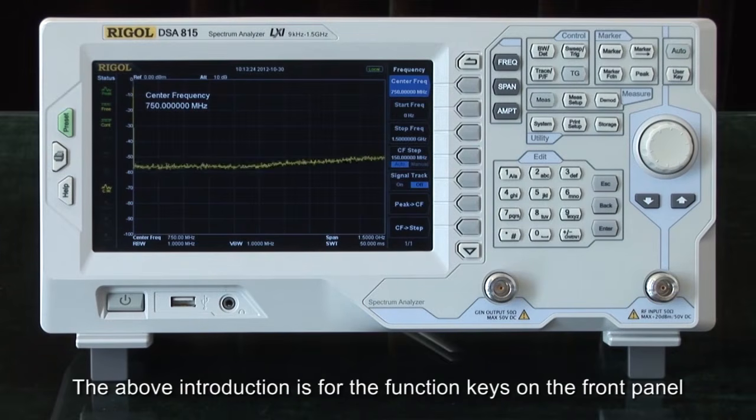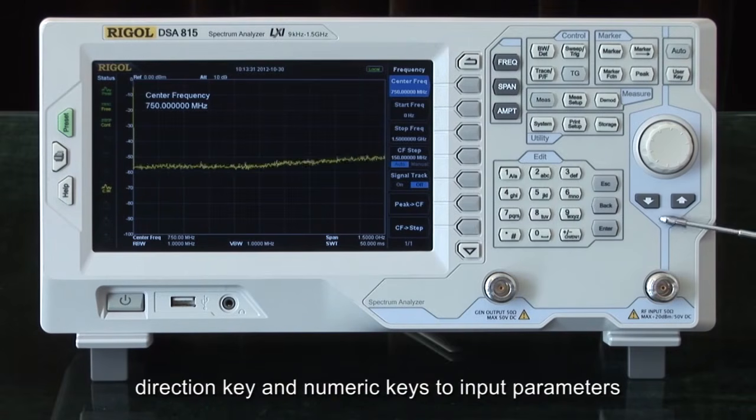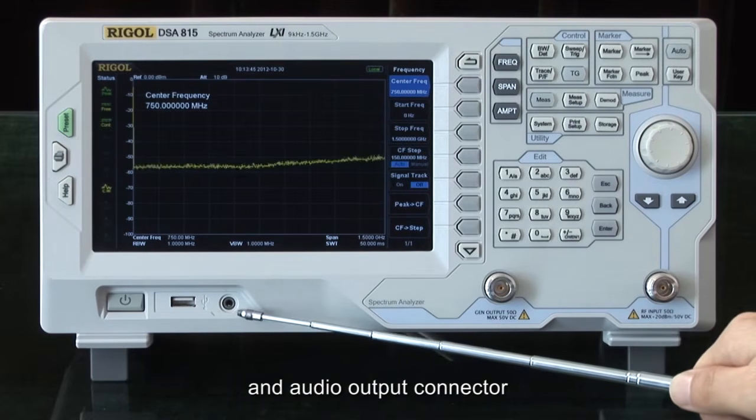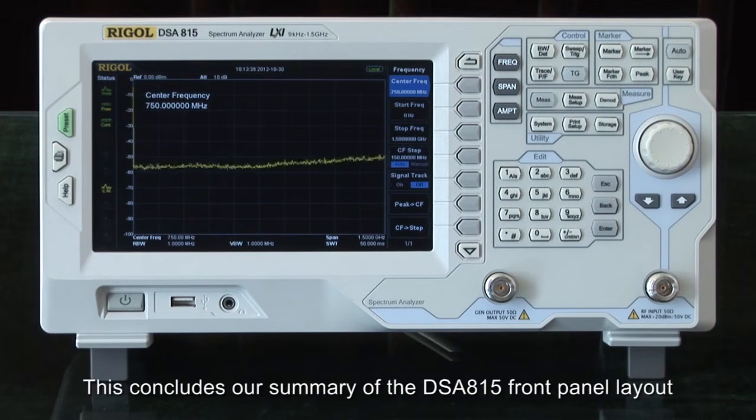The above introduction is for the function keys on the front panel. We can also use the knob, direction key, and numeric keys to input parameters. There are 4 connectors on the front panel: a USB host connector, an audio output connector, a tracking generator output if that option is available, and the RF input. This concludes our summary of the DSA815 front panel layout.